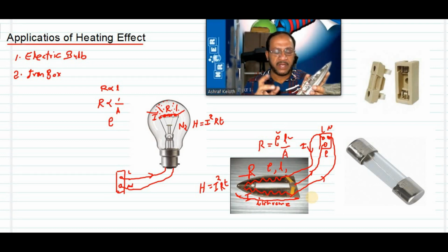So there are double precautions by using the earth wire here. Okay, we will come to the details of that when we are explaining about the fuse. And one more thing, the same thing happens in all electrical heating devices. Only the design will be different. If it is a geyser, a toaster or a sandwich maker, in any of these devices the main part will be a heating element, a nichrome wire, and you just pass current through that, and it will get heated up.